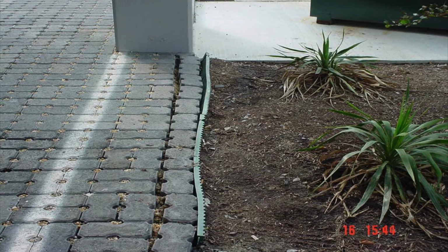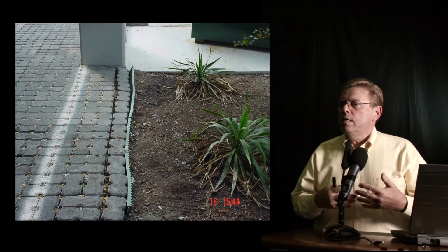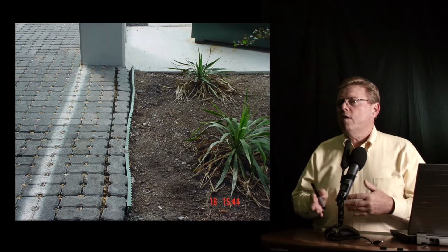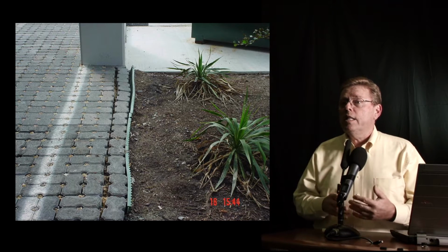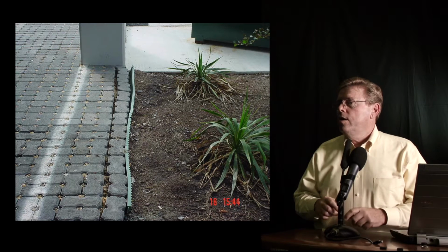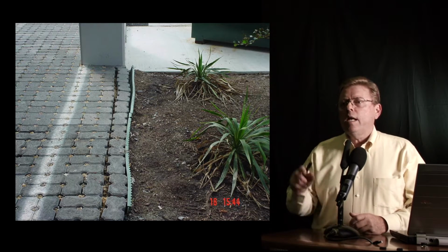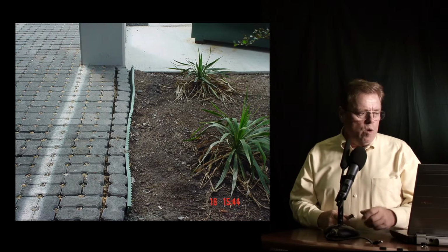Paver systems are very durable. Again, the paver is 8,000 psi. You're not going to break it. You can unweave it, so to speak. With braking and turning, if the edge restraint is not there, or if it's not laid in a pattern that's appropriate, or the paver doesn't have the appropriate aspect ratio, you can disturb it. And this is what we're trying to avoid.